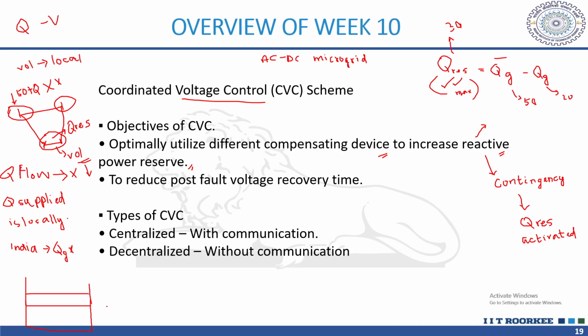See, firstly, as you said, if you consider the line rating in terms of S, that is a thermal limit for the line. So we always want the useful power, that is P, to flow in these transmission lines. Even if you send Q through the transmission line, no actual power delivery is done.